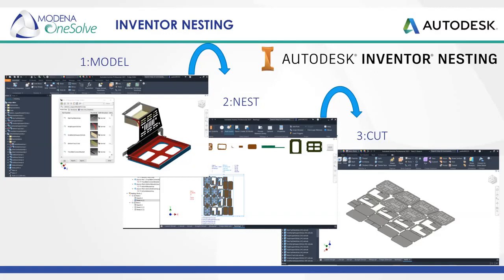So the Inventor nesting workflow can be broken down into three simple phases. The first phase would be creating your design or model as individual part files or grouping them into an overall assembly. These models can be created with Inventor by using the specialized sheet metal environment and the tools it has to offer. If the components are not your typical sheet metal parts, but rather something like wooden parts or profiles, the standard Inventor modeling tools can be used. These parts would of course need to have a flat profile and a unique thickness.